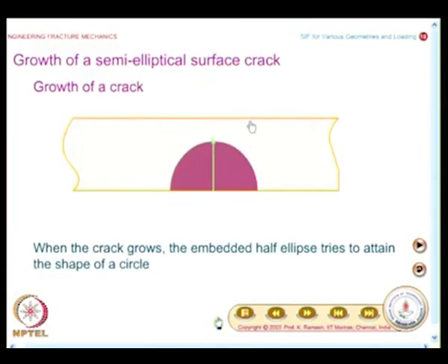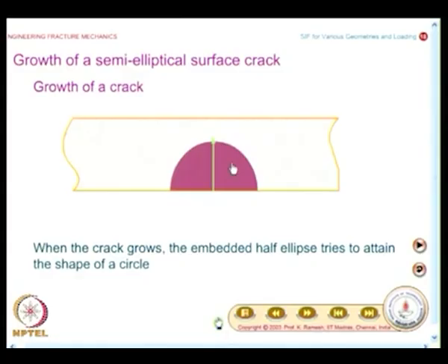Suppose the crack has become fully grown, then you can consider this thickness as idealizing a plane stress situation. When the crack has to move sideways, we would essentially use plane stress fracture toughness, and plane strain fracture toughness is less than plane stress. So, you have a good combination that the crack will open up and then touch the other end, then it will start propagating sideways.